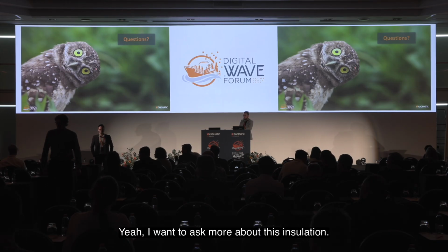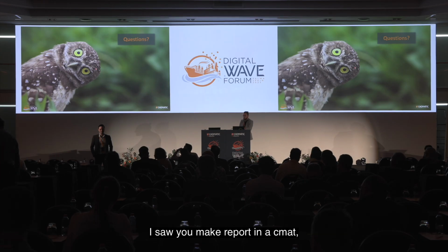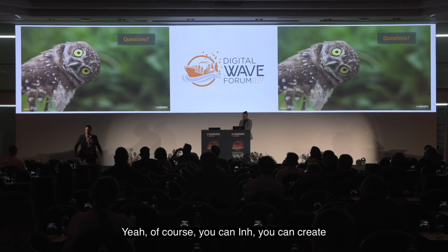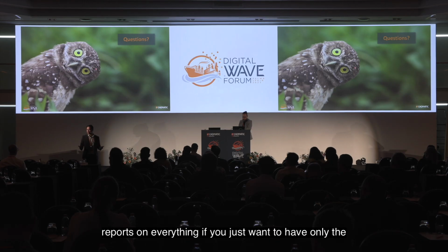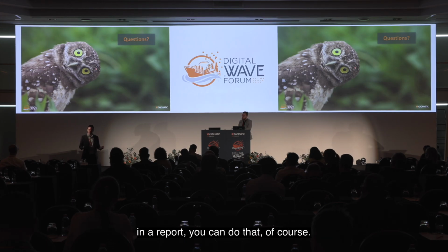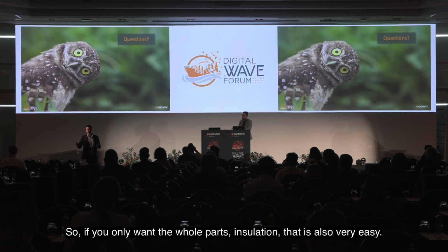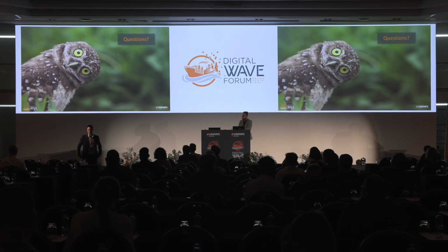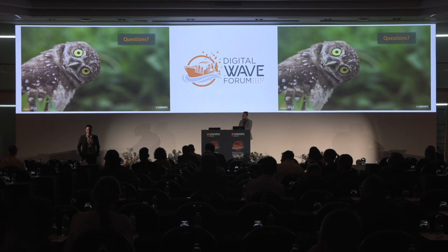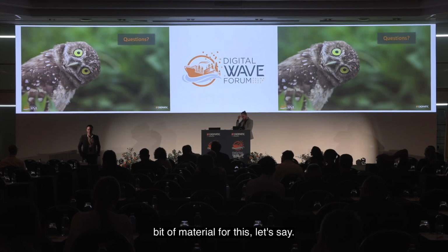Yeah, I want to ask more about this installation. I saw you make a report in Cadmatic Outfitting, but maybe I missed it in Cadmatic Hull. Does there exist some report for this installation? Yeah, of course, in Hull you can create reports on everything. If you just want to have only the material that I used, which was called SL720, in a report, you can do that, of course. It's just a material type like everything else. So if you only want the Hull part installation, that is also very easy.